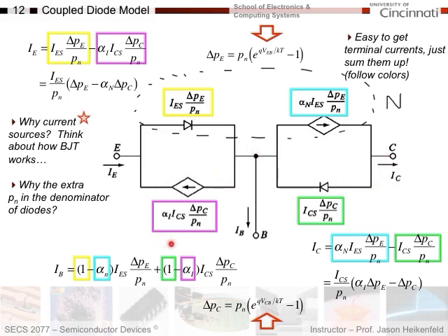And then over here, now my emitter is acting like a collector. Perfect. It's a current source, okay? And the current coming out this way is just the inverted current transfer ratio. Okay, I've got alpha I here, inverted current transfer ratio, times the current that was injected here. So how much of this injected current from the collector will come out the emitter? How much gets across the base? That's where current transfer ratio comes in. This is shown here, and the difference is the inverted current transfer ratio as it comes over here.